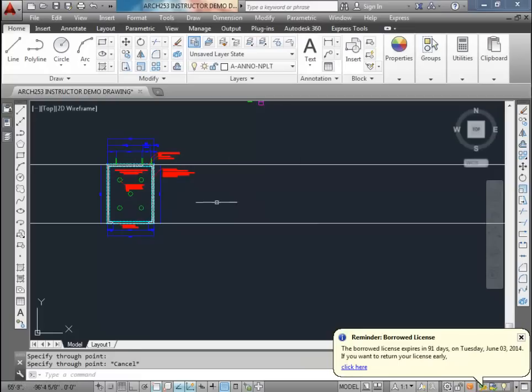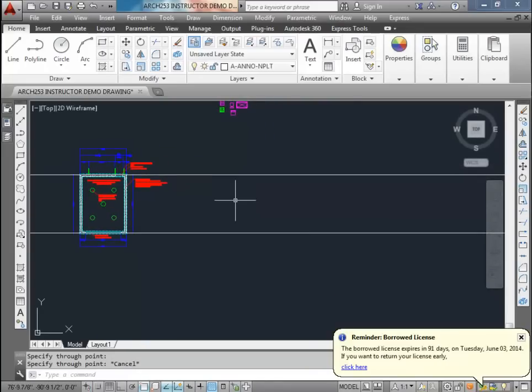So I'll have the foundation plan, the garage plan, and the main floor plan, so you'll be able to see what's going to line up. It makes it really handy, especially when you're looking at plumbing, where plumbing lines are coming down, things like that, or sewer lines, and you can actually see exactly how all these elements line up. Not only that, but it's also going to make it a little bit easier when you get to doing your elevations. We can actually use those reference lines for your elevation. Okay, so a little bit of an X line there. That'll get taken out later, but we'll leave that for now.